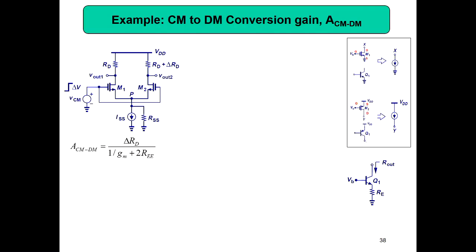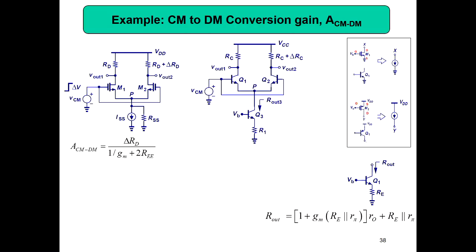In order to realize a current source with a high impedance, you will be using something like this. We will not be using a simple transistor. Instead, we will be using an emitter degenerated one, because only then you get very high impedance for the current source, since your R out will be a very big value. So when you design, you will design something like that. Even for R1, we can use another transistor, that is a cascode, when you realistically design it.